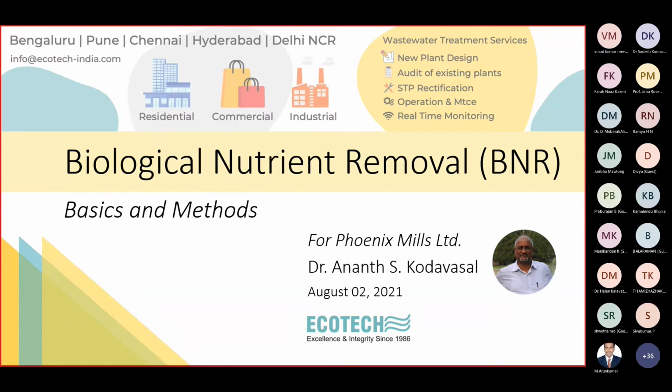This is recently, although it's a general presentation, we did a presentation to the Phoenix malls. In Phoenix mall we have recently introduced the denitrification stage. Earlier it was not required. Almost all of the STPs across India do not have a denitrification stage as yet. But all the new plants which we started designing about 6 months ago, we have introduced a denitrification stage, an anoxic stage following the modified Ludzack-Ettinger process for denitrification. And all the existing STPs which do not have this facility, we are now retrofitting a denitrification stage.